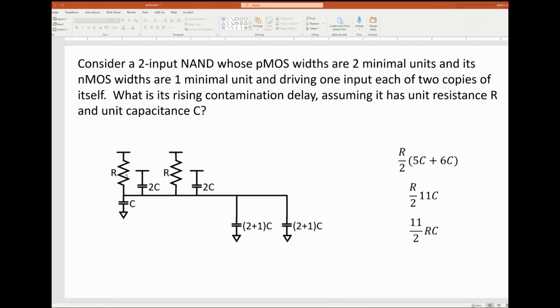of all the gates along the minimal path versus the propagation delay of all the gates along the critical path. If the minimum amount of delay is too low, then you violate the hold time, and if the maximum amount of delay is too long, you violate the setup time. So that's a topic I do in 611 under timing closure, and that's why this is important. But in this case, we only are looking at why there's a difference between contamination and propagation delay.